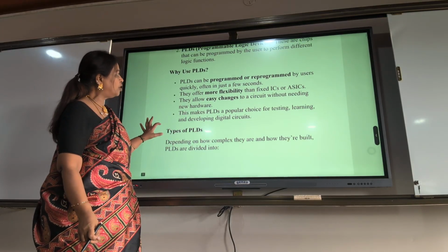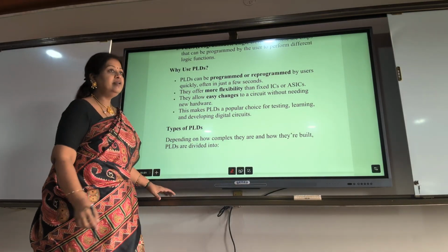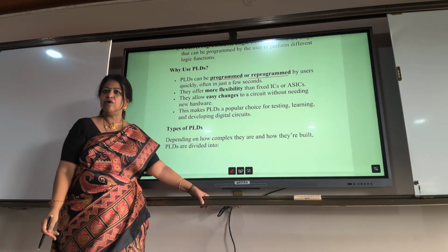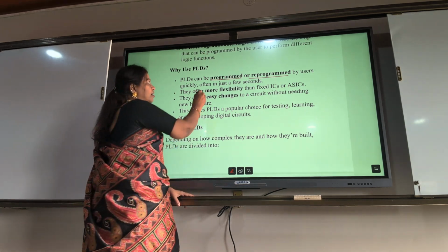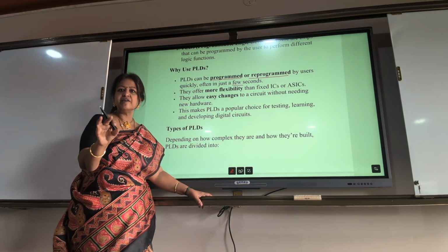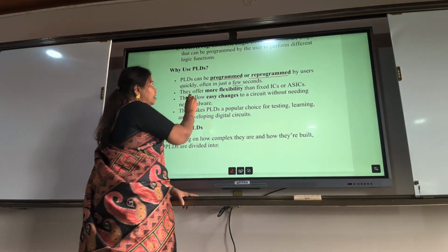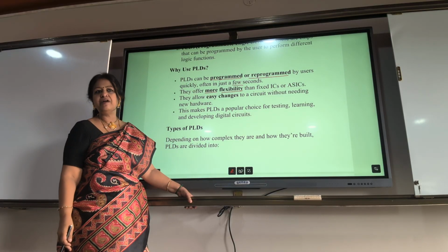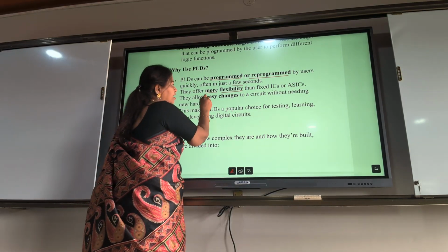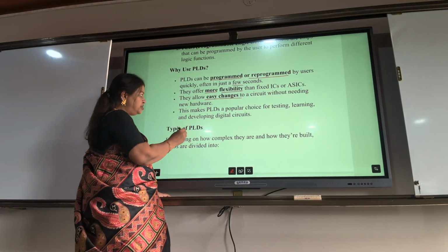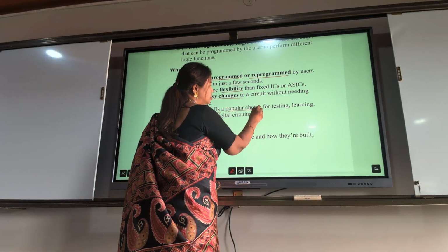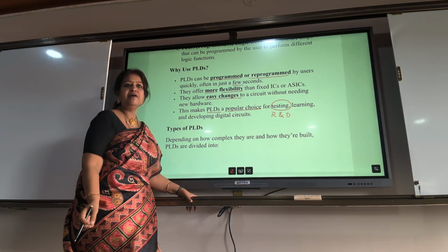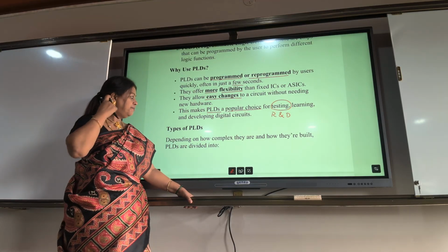So why use programmable logic devices? The convenience is we can program or reprogram. If you want, you can change the program, or put in whatever program you want. In just a few seconds, you can change the program of the IC. They offer more flexibility than fixed ICs or ASICs, and they allow easy changes. This makes PLDs a popular choice for testing, especially for R&D, research and development. You can reprogram a number of times.